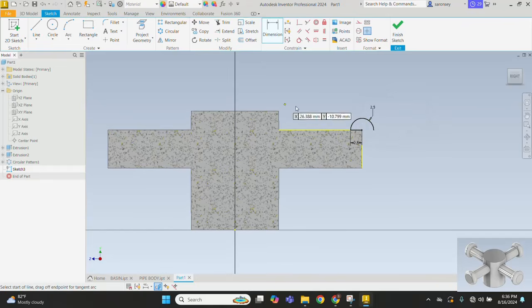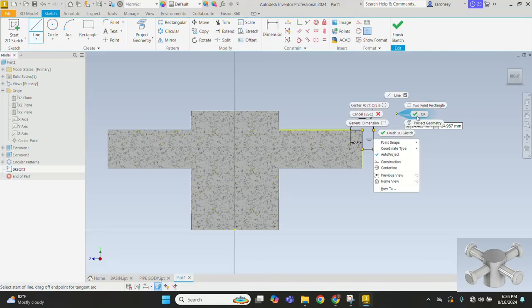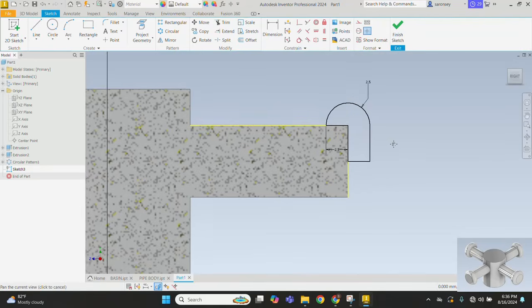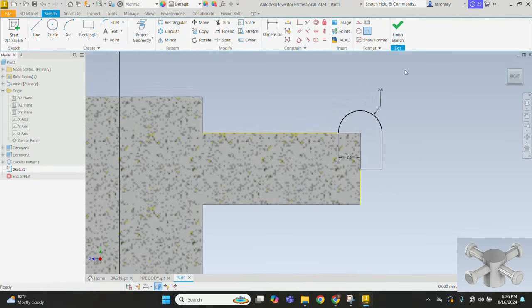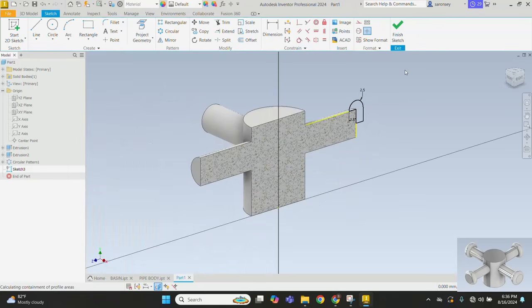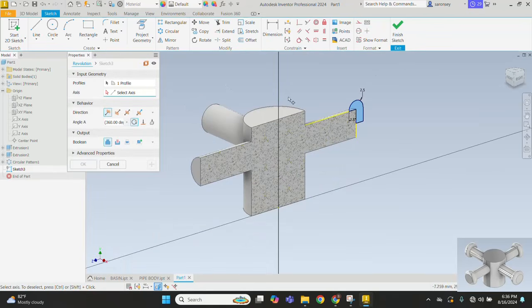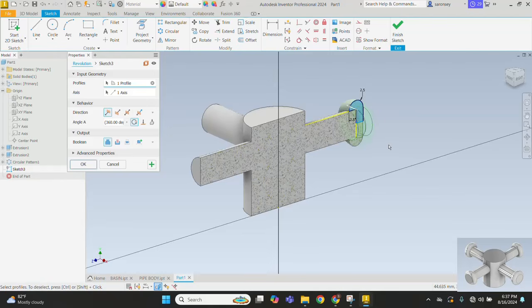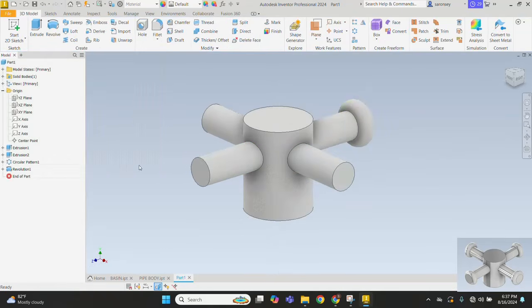We'll pick the line command. Let's draw a line here, making sure we locate the midpoint of that vertical line close to it. So there we go. And we'll drop this here. Okay, we can even connect this and that one. Right click and then OK. Now our sketch is fully defined, and so I would press R straight away to revolve. The axis of revolution, we'll choose this one. Okay, we see a preview of that. It looks good, and so I would okay.